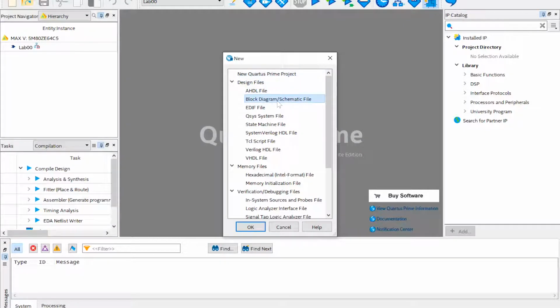One of the things that's nice about Quartus Prime Lite, and Quartus Prime in general, is that you can actually do something as a schematic. If you know what an AND gate looks like, if you've already had a class that shows you how to draw schematic diagrams, this is really easy because you can basically just reproduce it in software. Then obviously you have to tell the software what your hardware inputs and outputs are, but it's really easy to use, with a really low learning curve.